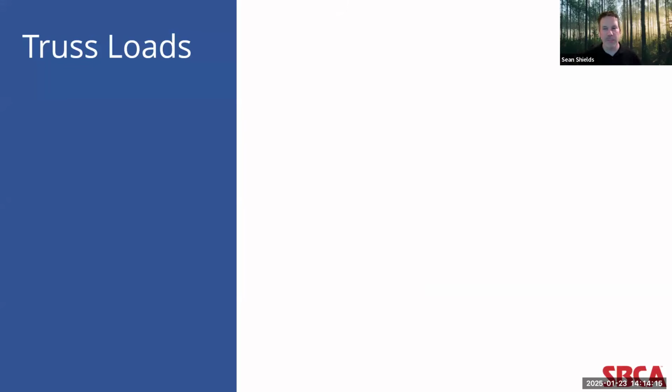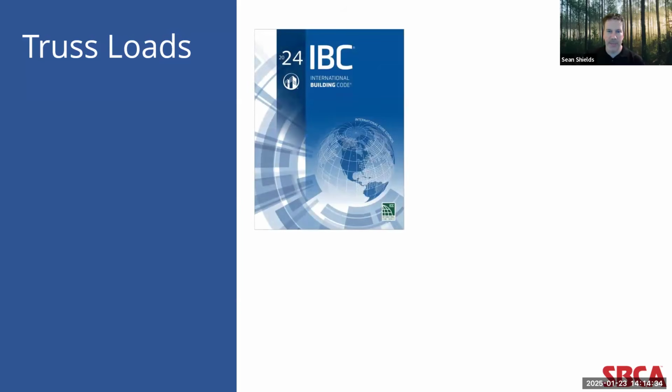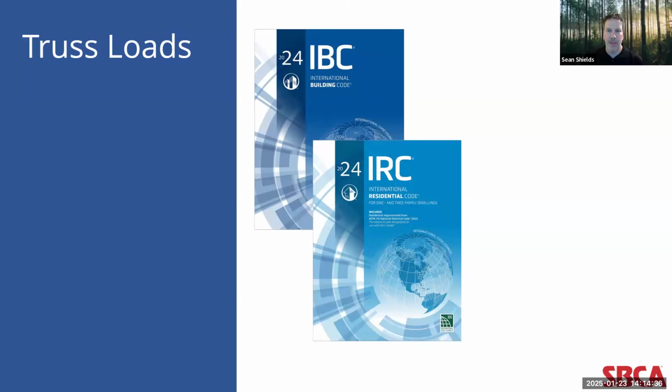Okay, so after truss spacing, the next thing to check on is the loading conditions of the truss. These are the design criteria the truss designer inputs into the design software ahead of time, based on a wide variety of inputs from anything like the applicable building codes, so the IBC or the IRC.